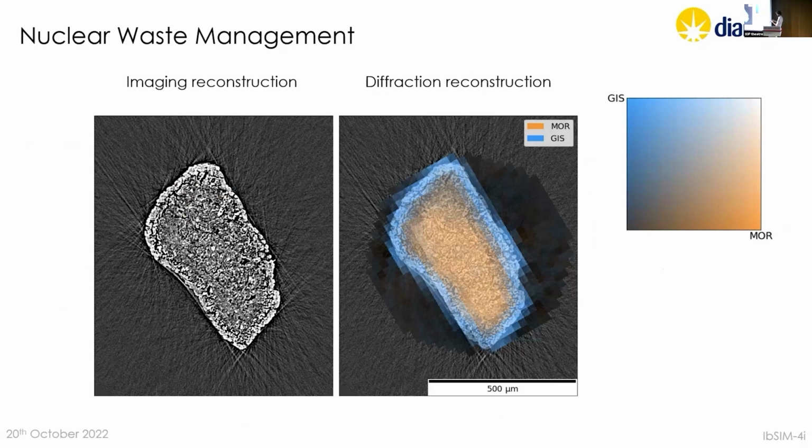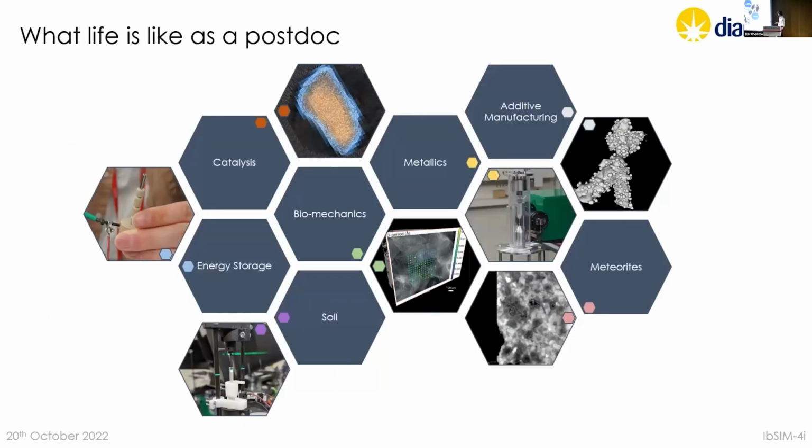So you can see here the grayscale values of a 2D slice through that structure. And when we combine that with the diffraction measurements, and you can see the different positions of this around the data set, we can then start to identify the different crystal structures, and we can then characterize the gismondine and mordenite phase. And we can actually then see that this was formed on the surface. Maybe we could change the manufacturing method, form the pellets to be smaller or something like that.